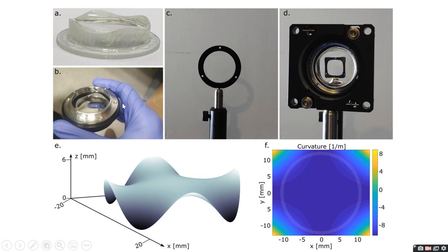I would like to note that this method does not depend on any specific optical liquid. We used a wide range of different polymers, both photocurable and thermally set ones. In principle, any curable liquid can be compatible with the fluidic shaping method, as long as the appropriate immersion liquid can be identified.